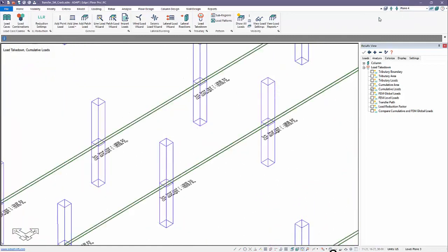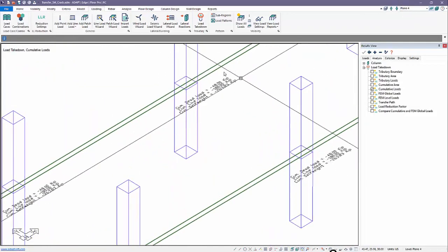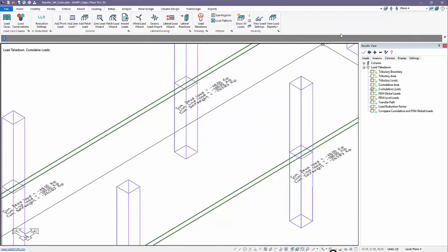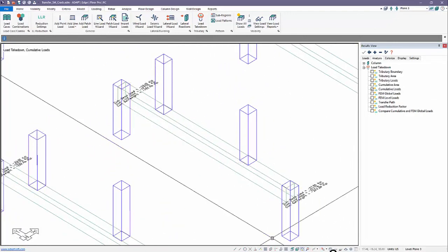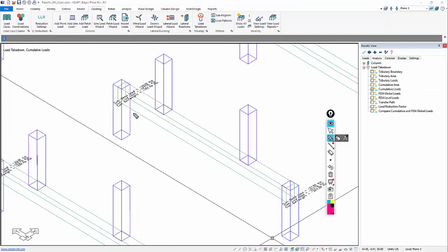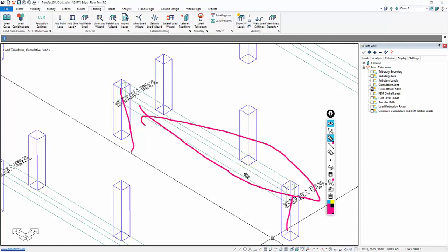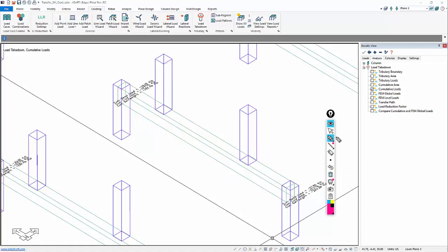So when I go from this level 4, this set of loads, 48, 180, 263, that actually gets split, and ultimately it will end up down in these columns. But we want to evaluate these beams in this level. So this just gives us the ability to then use those reactions in these columns when we analyze this one floor in isolation.